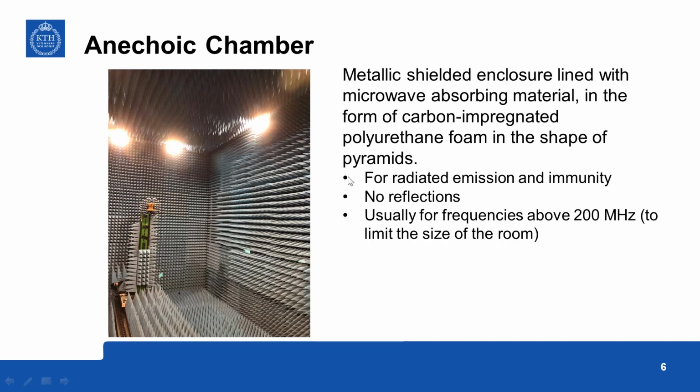Anechoic chamber. This is a metallic shielded enclosure lined with microwave absorbing material in the form of carbon impregnated polyurethane foam, and these foams are shaped like pyramids.